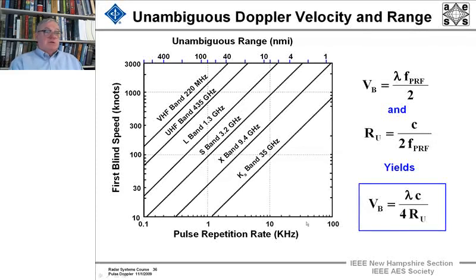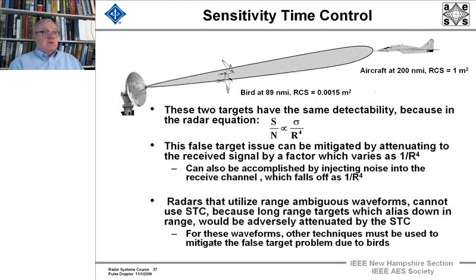Now, when we send out bursts of pulses and make a set of Doppler filter banks, there are going to be some notches where the blind speed is, where we're ambiguous in range and ambiguous in Doppler. And what we do to handle that is a number of things. But first, before I go through those, what I'd like to do is bring up the issue